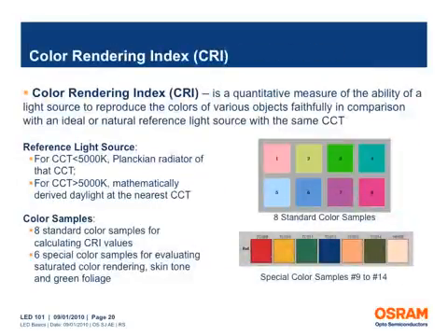The color rendering index, or CRI, is a measure of a light source's lighting quality. It's an index rating commonly used to represent how well a light source renders the colors of objects that it illuminates. For a CRI value of 100, the maximum value, the colors of objects can be expected to be seen as they would appear under an incandescent or daylight spectrum of the same correlated color temperature.